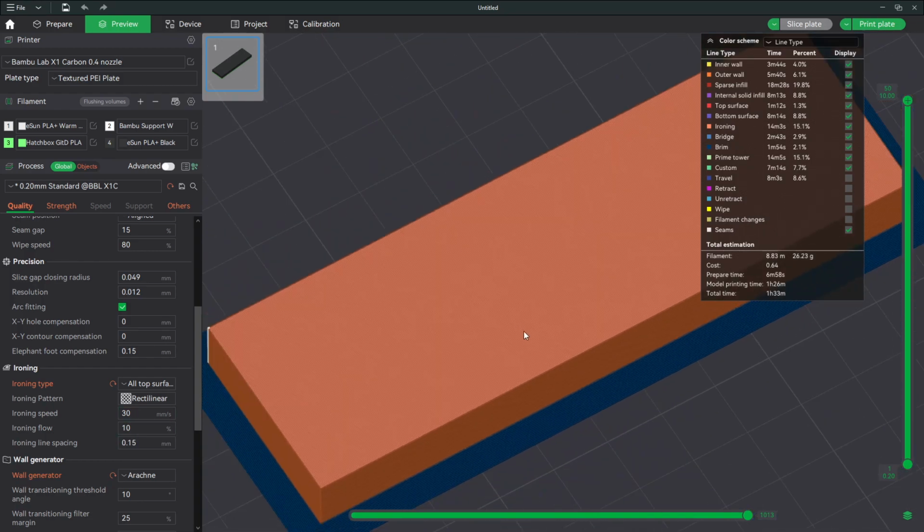If this surface is not level, it's going to run into little sags, little valleys in between where the infill walls were. And it's going to kind of pile up. And then it gets to a high point where that infill line was underneath, and it'll look good. And then it'll go back into the next little valley. And you end up with a very inconsistent surface.